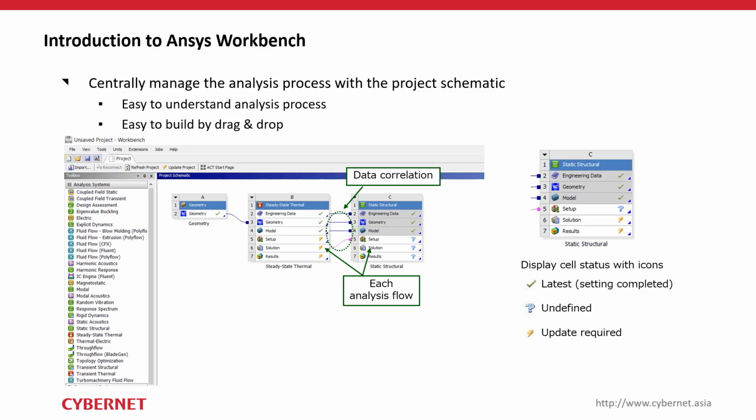As you can see right here on the screen, we have the setup of a thermal stress analysis. You do the thermal analysis, and afterward you do the static structural analysis to evaluate the stresses. With Ansys Workbench, you can easily drag and drop these analyses into the project schematic, connecting them together, and manage all of your analysis in a more comprehensive and constructive way.